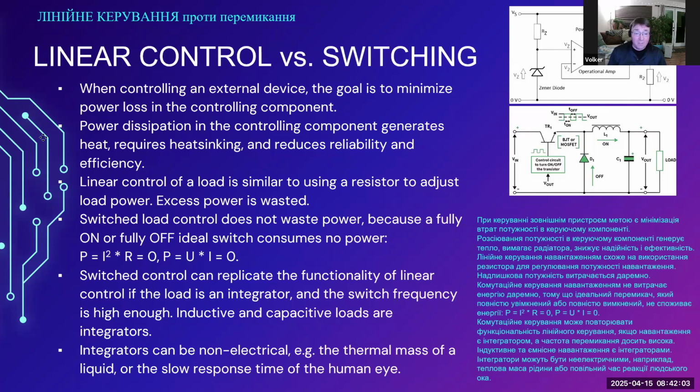So the LED might be flashing at 1 kilohertz frequency, and with a PWM that makes the LED appear brighter or less bright. But because the human eye cannot follow the fast switching frequency and effectively integrates this, you can happily drive an LED with a relatively high frequency PWM, and it will look as if it is driven by a changing voltage or a changing current in this case.